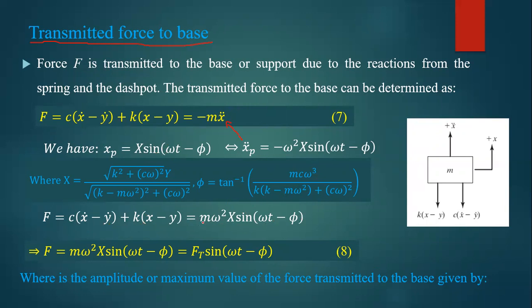This seems like a kind of centrifugal force, m omega square r type, with centrifugal acceleration equal to omega square r. It actually works for the rotating unbalanced case with eccentricity e, m omega square e.